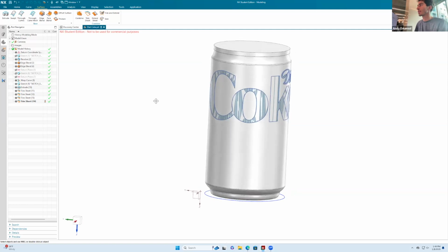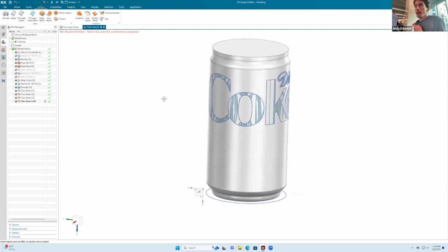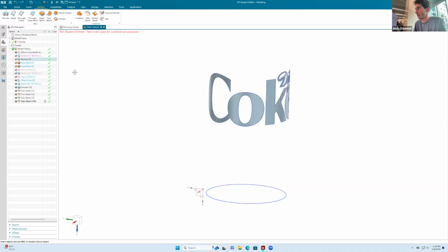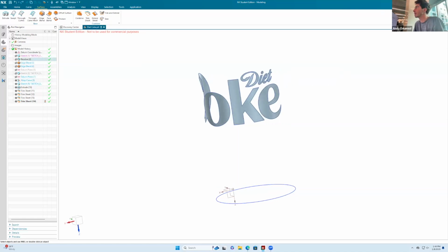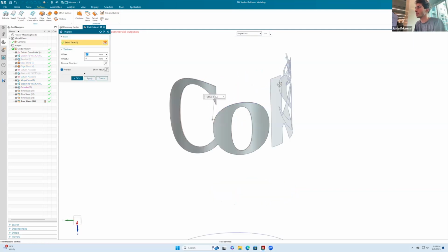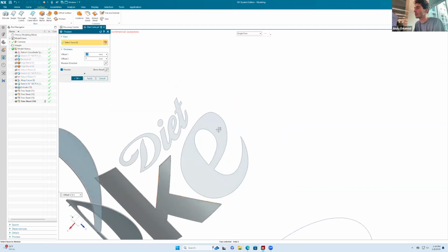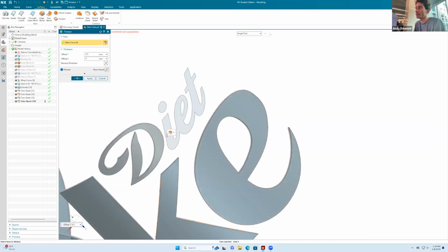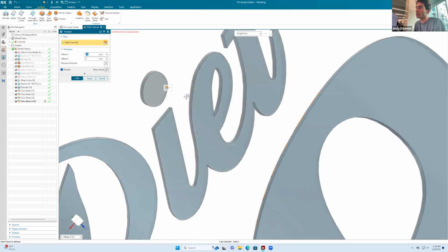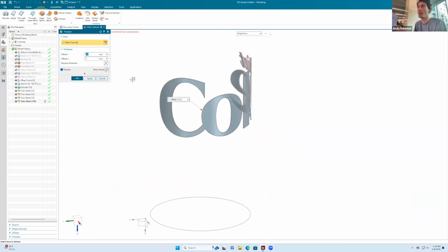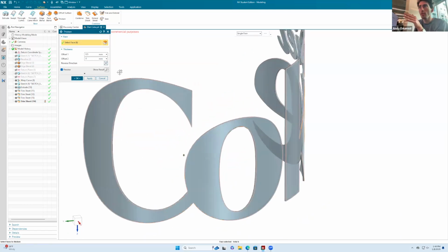the revolve. So that's what we have. We're left with all of this. Again, actually, maybe I don't want to show anything. Go here to thicken. I'll select all of these guys, but I will actually thicken in the reverse direction, inwards, and only by 0.1.